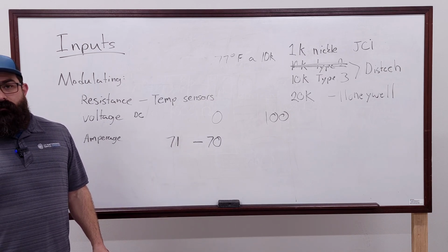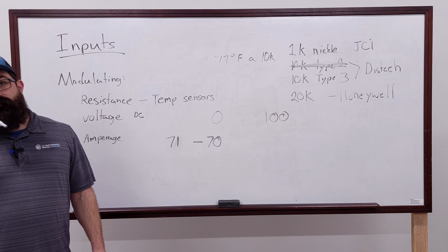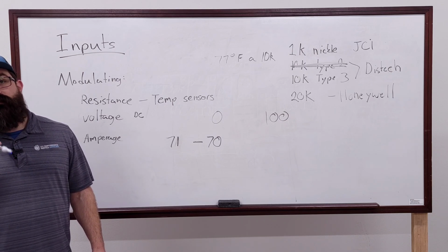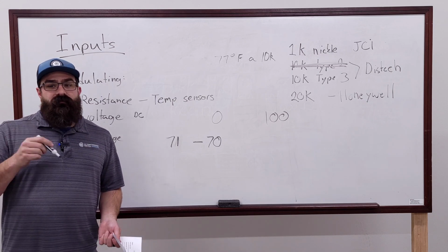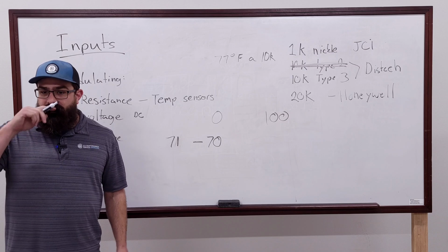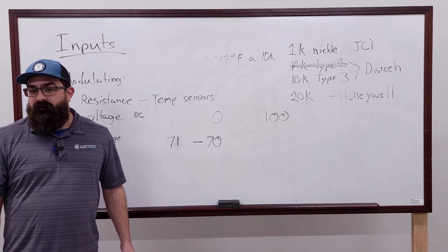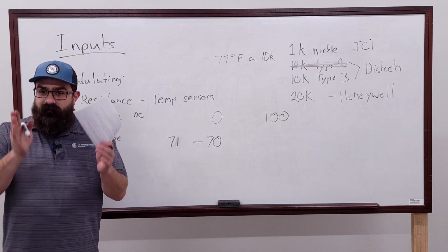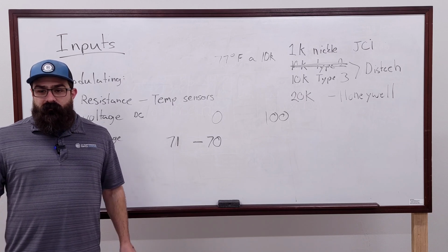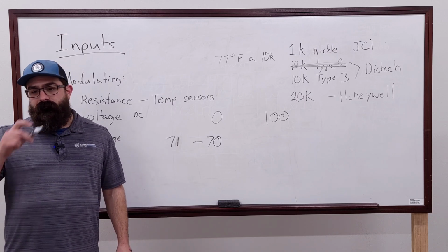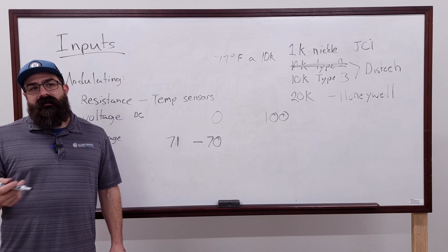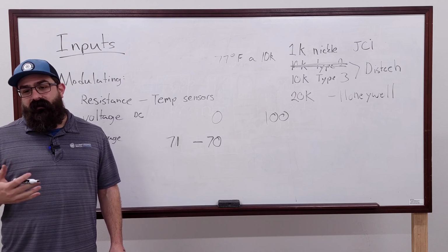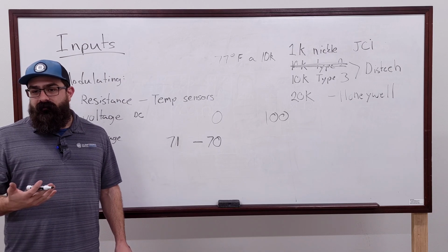Like Honeywell, as long as we use the correct impedance wire, which is basically resistance per foot, up to 300 feet, I don't have to put any calibration. It's pre-done in the controller. That input is already set up like that. And I think that's kind of why they come up with the 3% variance too, to account for that.